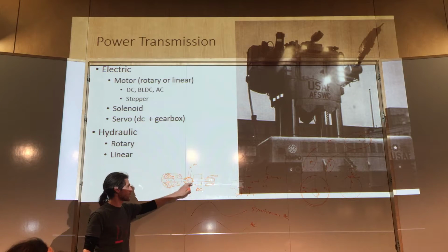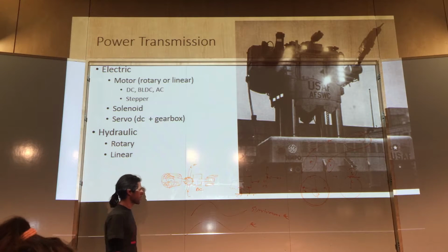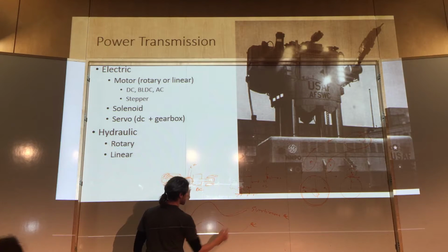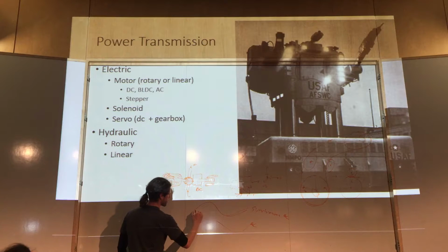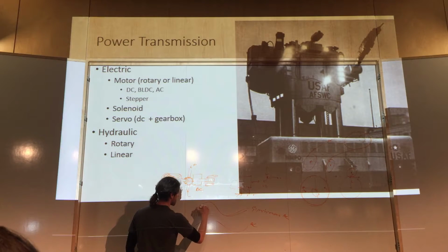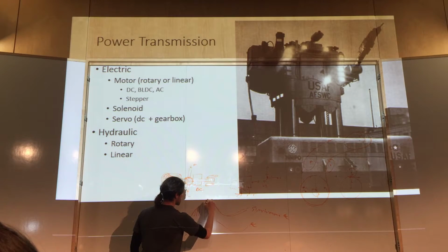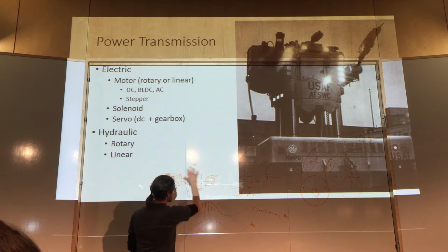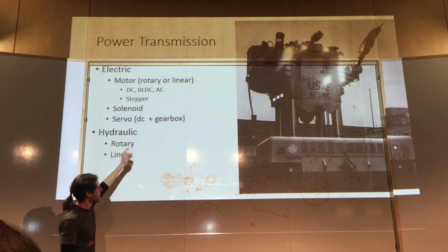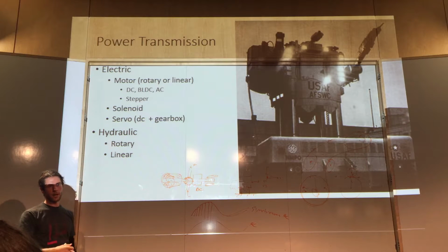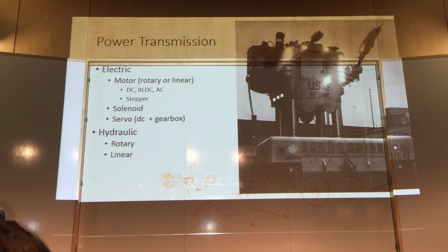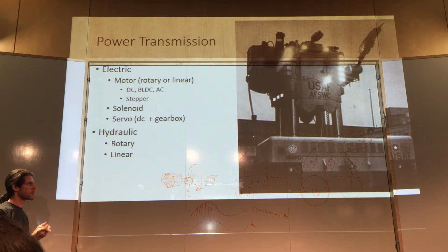Synchronous AC is basically the exact same thing as brushless DC, only it has this nice smooth curve, whereas with the DC motor, you're actually PWMing to generate the signal. But in all these non-stepper motor configurations, you need feedback in order to get to some sort of position. The stepper is beautiful because you can just run open loop, you just count the steps and that's where you're at, hopefully, as long as you didn't run into anything. But if you want real precision, you need to close the feedback loop so you really know where you are.